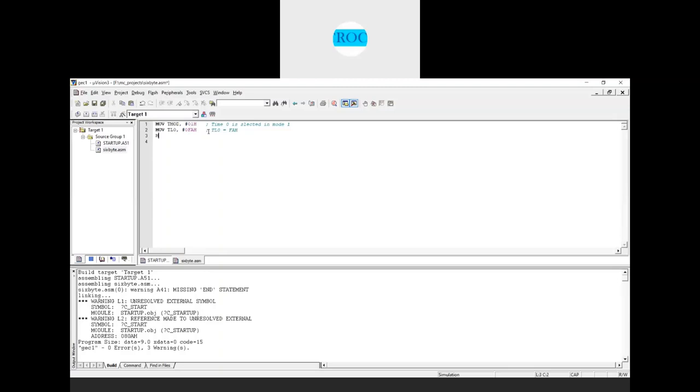FAH there. Similarly, MOV TH0, #0FFH, right? So the TH0 is equal to what after executing this one? It will be FFH. We initialized the TMOD register, the TL0 register and the TH0 register. Next, you need to start the timer.